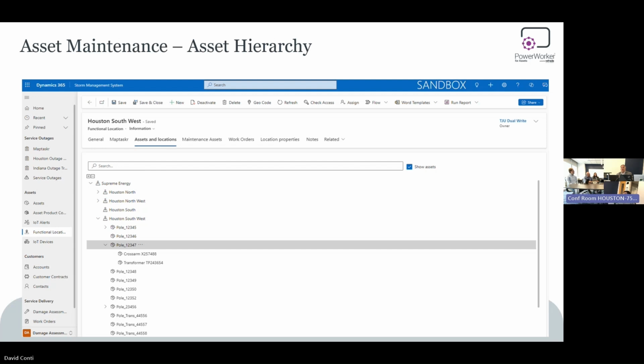And then from there, maybe some condition-based maintenance, based on maybe other external factors, weather that could be impacting things. So go perform some maintenance. And then predictive. So understanding, hey, based on some data that we have, we think after X number of hours, this piece of equipment is going to go ahead and fail. So let's get ahead of it before we've got a customer issue.